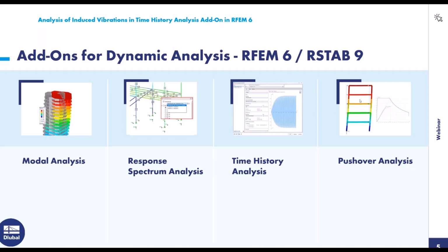I will go now to the right side because that's the pushover analysis. It's more familiar to the response spectrum analysis because here we are able to do a pushover analysis for structures. Therefore, we can calculate the capacity curve of the structure, and we are able to do the pushover analysis for such a structure with nonlinear hinges according to FEMA or according to Eurocode if you want. Yes, of course, and then you get the response for that, also in the nonlinear case.